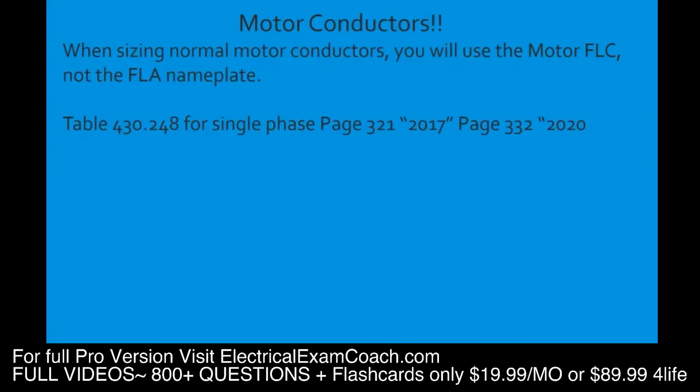One thing I want to note is that these are nominal voltages. So although it says 115 at the top, it would also include 120. Although all the way at the end it says 230 volts across the top of the black bold headings, you could still count 240 in that. Another tip is that even if the motor is a single phase motor, but your question states 208 volts, you use whatever column your question states. Don't try to use reasoning and say, well, 208 is only three phase. Whatever your question states, just do it that way.